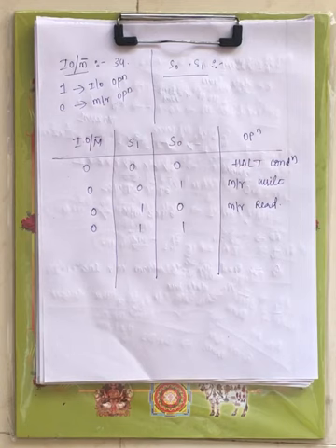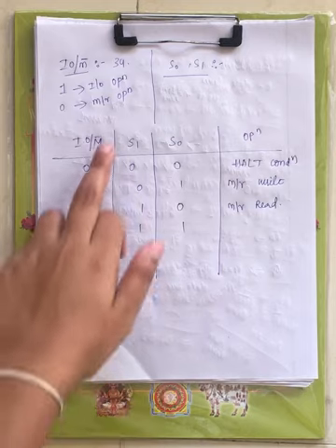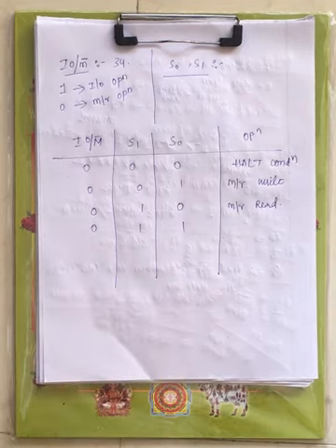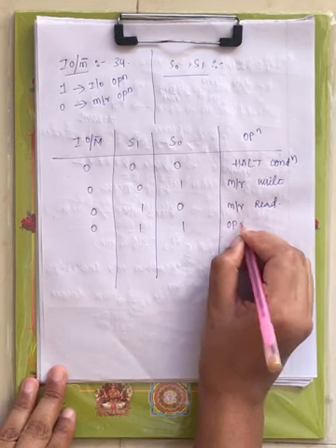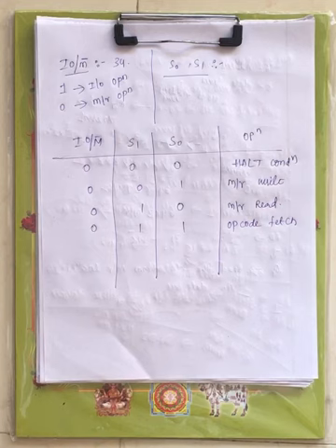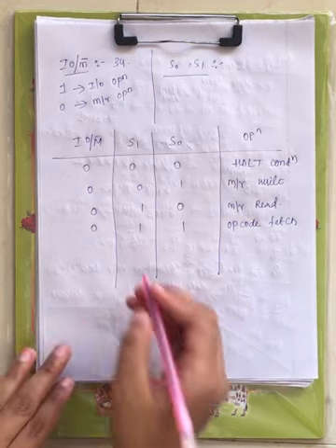Opcode is nothing but the binary form of an instruction. We have seen the 3 steps of the processor, that is fetch, decode and execute. Where are you fetching the opcode from? From the memory, that's why IO/memory bar is 0. When both signals are high, that indicates opcode fetch.